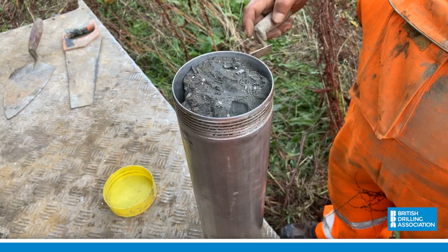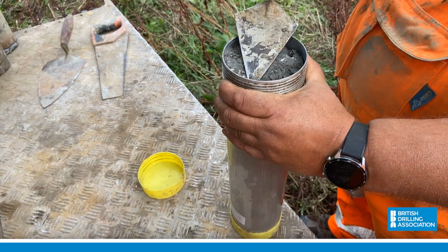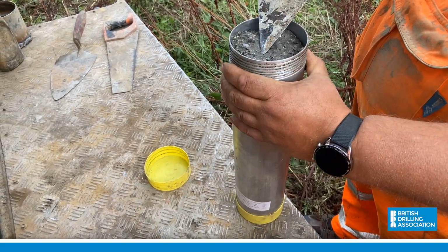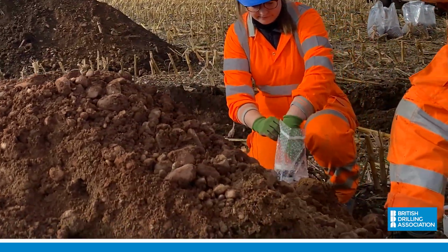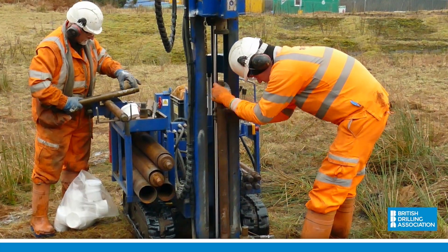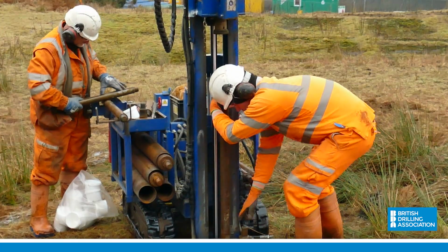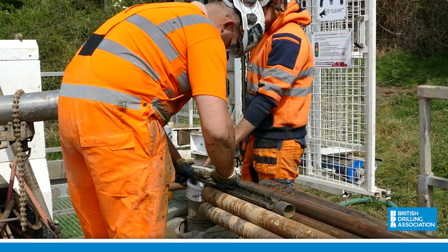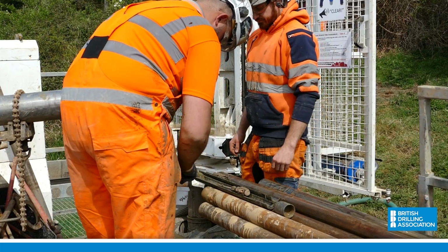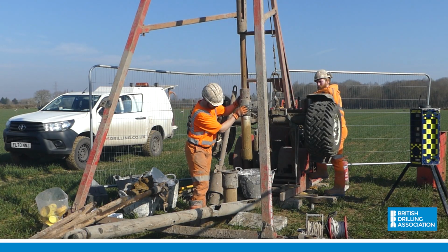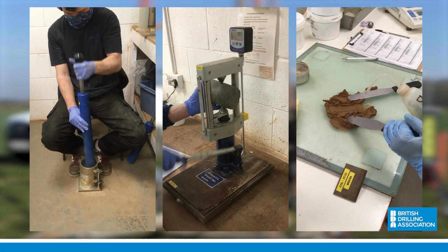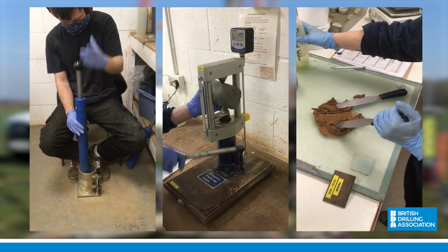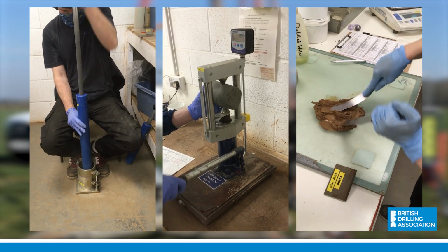A typical ground investigation will require the driller to obtain a number of different sample types. There will be samples specifically taken to assess if contamination is present, and then a variety of disturbed and undisturbed geotechnical soil and rock samples. These are taken to determine design parameters. The quality of the samples taken will determine the type of laboratory testing which can be acceptably undertaken on them, and the reliability of the test results obtained.